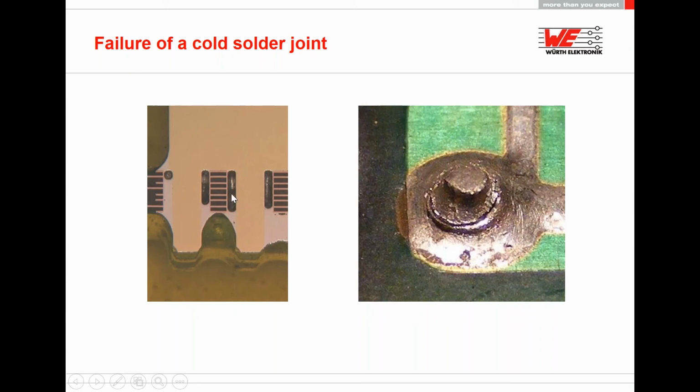You can have air bubbles in it. The solder joint can be not perfect, and then you increase your resistance again, and that makes it a little bit dangerous. And as mentioned before, if your solder joint is not perfect, resistance is increasing and the whole application can be damaged. So the number for current is about 100 amps for soldering technology.